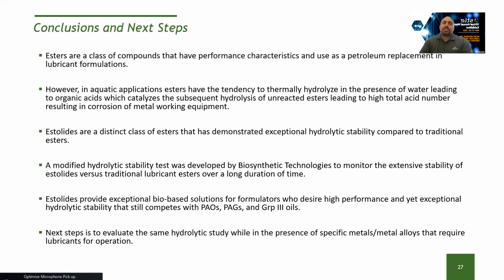Estolides are another, very distinct class of esters. From the research I've presented today, I hope I've shown that they have demonstrated very high hydrolytic stability compared to other traditional esters, and that they perform very close to, and behave like, PAOs in terms of hydrolytic stability.